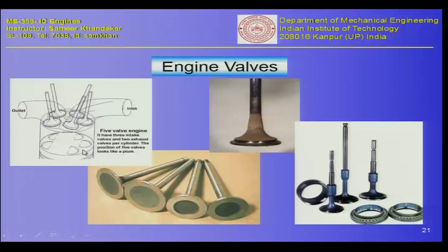The reason for this depression, why you want to take the piston all the way up and reduce this particular volume, is related to thermodynamics and the combustion process, which we will of course take up as we go ahead. Why do you want this volume to be of a certain dimension? The combustion chamber has to be of a certain dimension, and why do you want to make this piston as close as possible on the top, how close can you go, how much reduction can you do in this volume, and how is it related to the type of fuel you are burning and the thermodynamics of the process? We will definitely talk about it in later lectures.